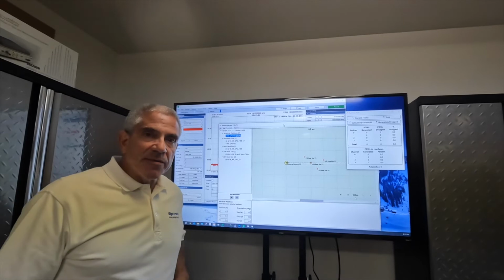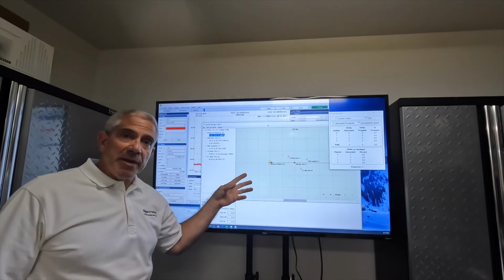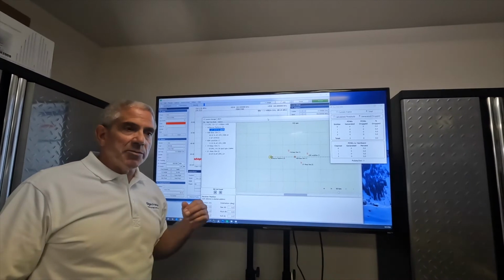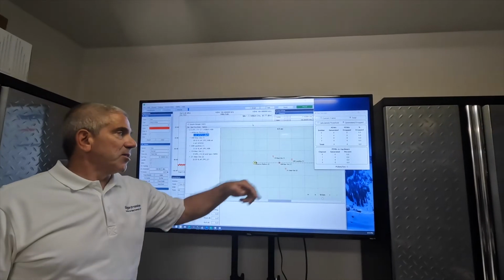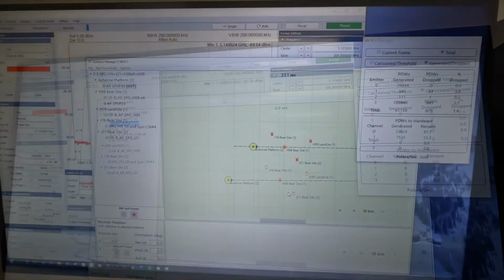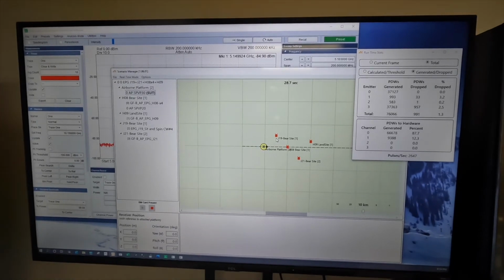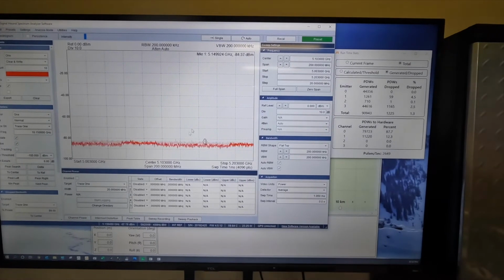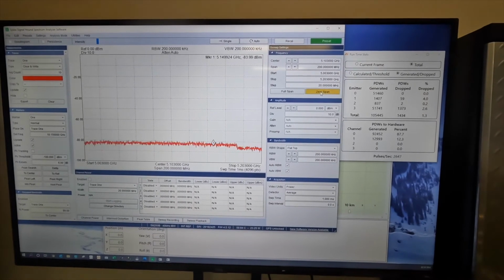So one more thing I want to show you before we break is the pulse characteristics. We've seen it in the frequency domain on the normal spectrum analyzer display. We're going to put it in zero span mode and show you some of the pulse width and PRI characteristics of H08, the guy that we're flying radially into. So as we've seen, this is our airborne platform flying into our H08 emitter, and we're going to start up in the frequency domain on the normal spectrum analyzer display, and then we're going to switch over to the zero span mode and show it to you in the time domain.